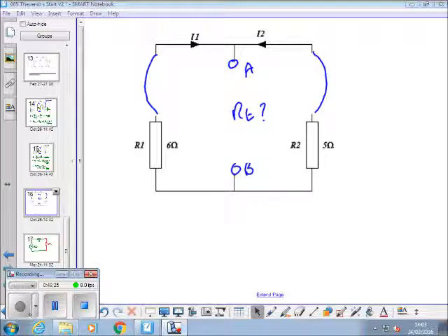Start video now. Right. So the last thing we've got to find, haven't found our Thevenin's voltage, is we've got to find our Thevenin's resistance. So if I connected an ohm meter in there, what would I measure? What kind of circuit have I got? How are those two resistors connected? Forget about the current for a minute, let's cross them out. If I put an ohm meter in, think about this. How could I draw this circuit differently that would help me?